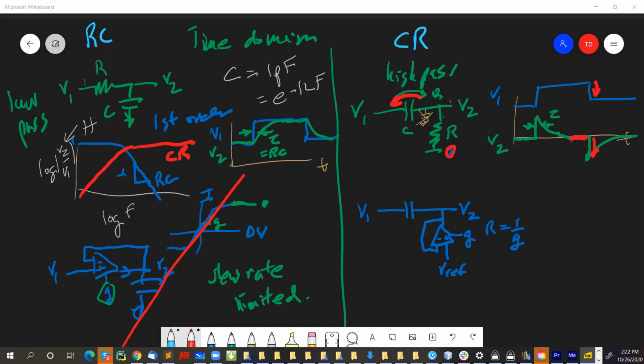Yeah, you're asking, what is this frequency here, right? Where they cross over. Yeah, exactly. So tau is a time. So 1 over tau is a frequency, but it's not quite 1 over tau. It turns out it's 1 over 2 pi tau. This corner frequency right here, I should draw in a different color. It's not red or blue. It's green. Okay, well, choose green, right?